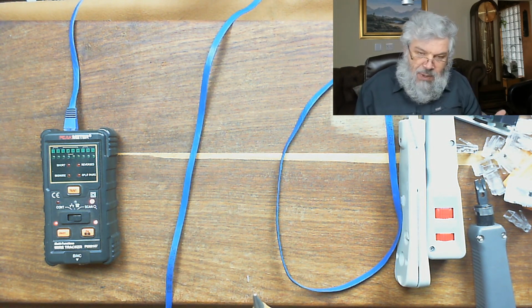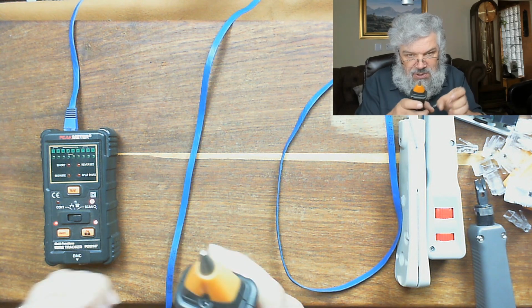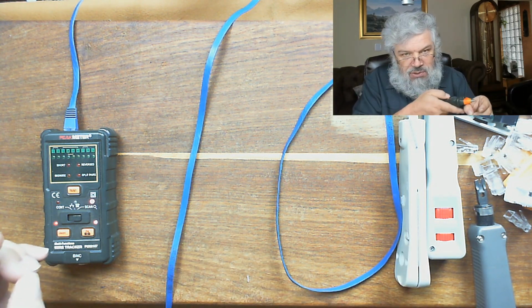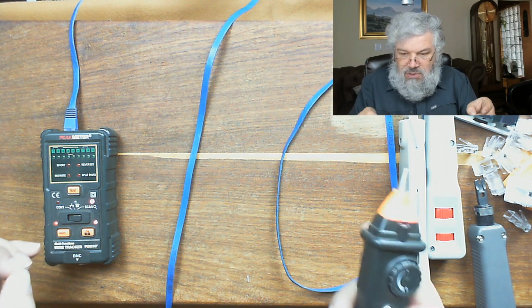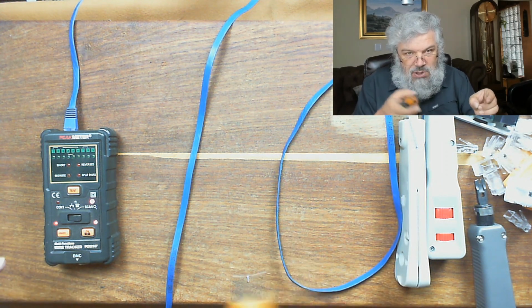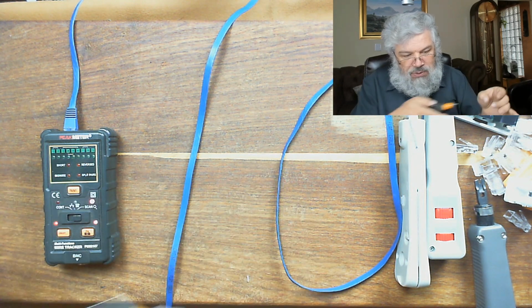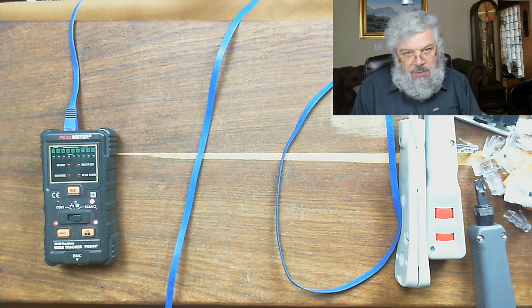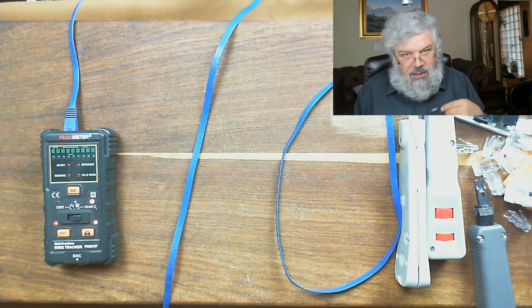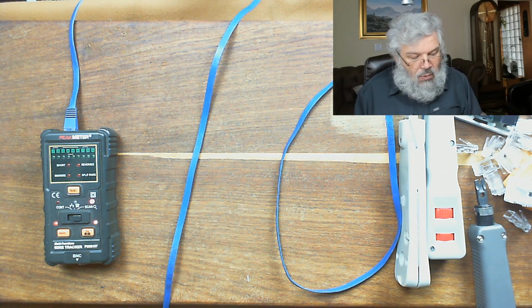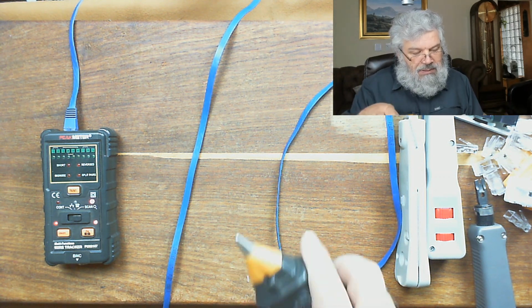In fact, the way in which you typically use it is you split the bunch of wires into two, and then you hold this into the one bundle and into the other bundle, and then you know in which bundle is your endpoint. And then in that bundle, you split that bundle in two again until you find the appropriate one, because it's pretty hard to trace all the cables from throughout your office complex or your house to all the various endpoints.